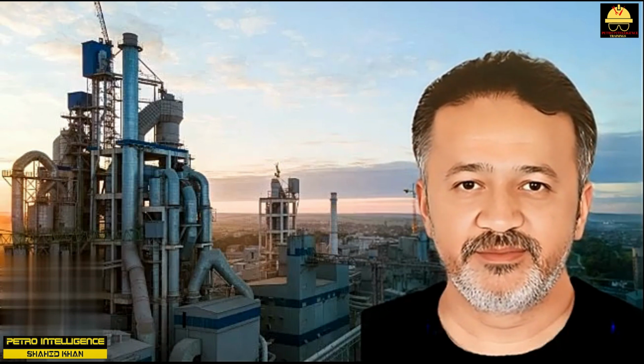He designed a new bundle, using the existing shell and nozzles, with new tube support baffles. He mostly eliminated the parallel component of shell side flow. The observed heat transfer coefficient improved to 80 BTU per hour per square foot per degree F. The increased thermosiphon driving force resulting from the larger reboiler duty and vapor generation rate offset the increased pressure drop caused by the new baffles. This kept the circulation rate through the shell constant.